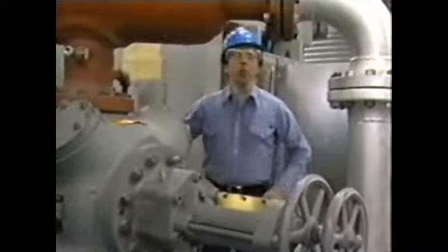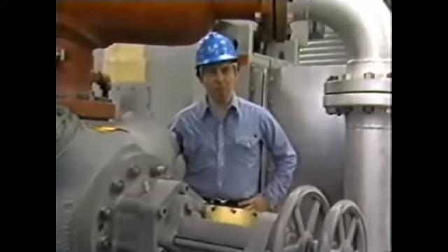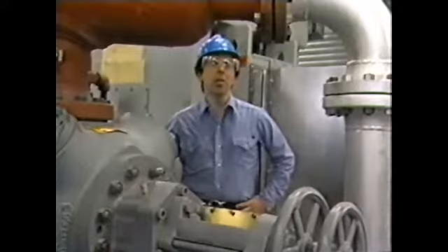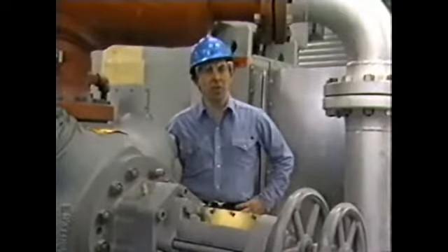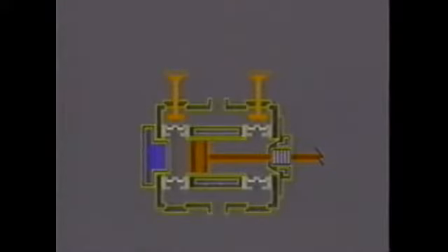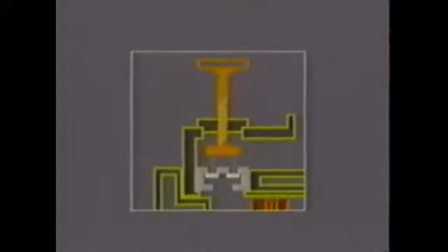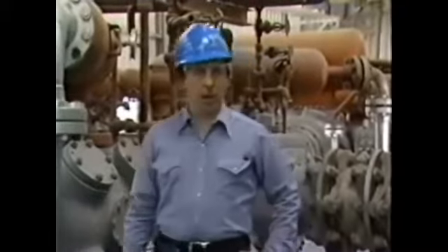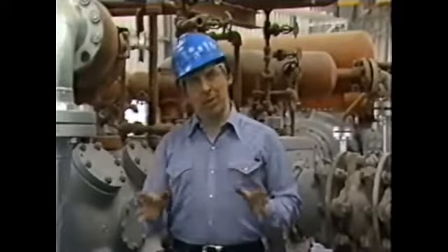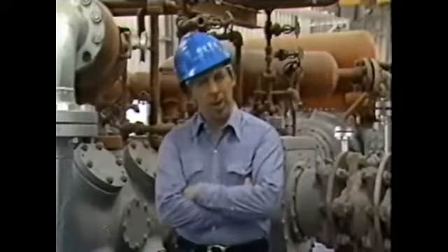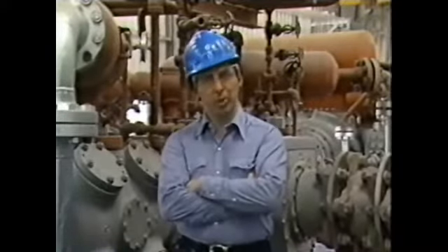Under normal compressor operation, the suction and discharge valves open and close relative to the piston position. However, the valves may also be equipped with devices called unloaders. An unloader is used to alter the load on one end of the piston. By unloading or opening the valve, we decrease the capacity of the compressor. Like a clearance pocket, unloaders may be operated either manually, using hand wheels, or automatically, using a device called a pilot, which uses suction or discharge pressure.